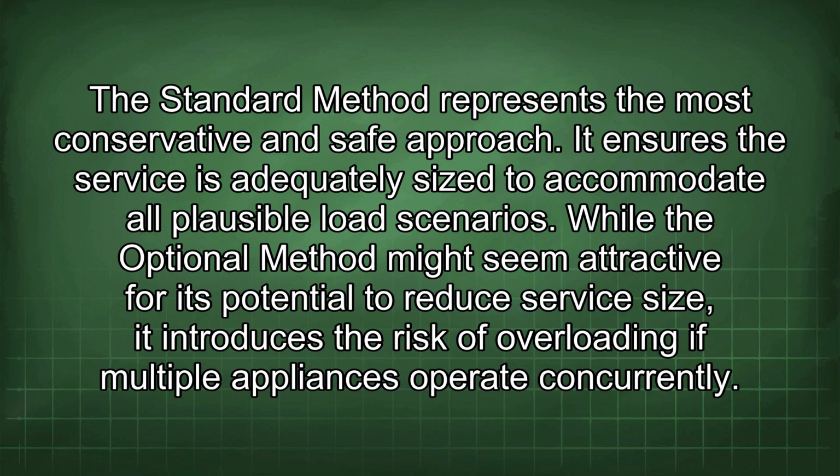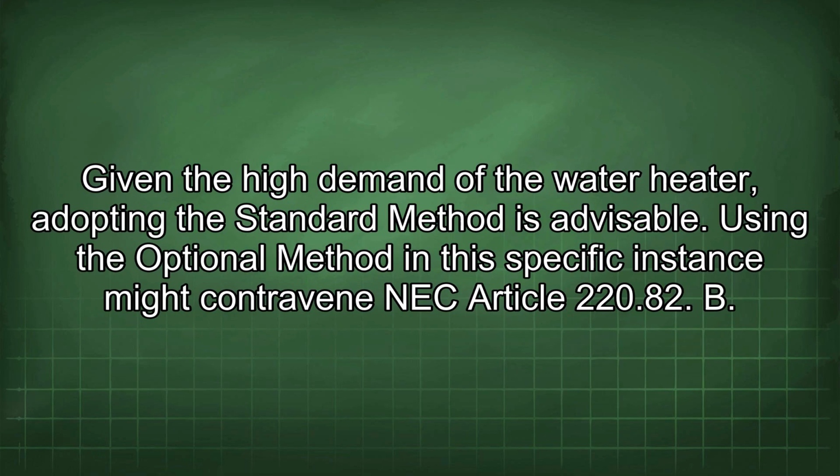It ensures the service is adequately sized to accommodate all plausible load scenarios. While the optional method might seem attractive for its potential to reduce service size, it introduces the risk of overloading if multiple appliances operate concurrently. Given the high demand of the water heater, adopting the standard method is advisable.